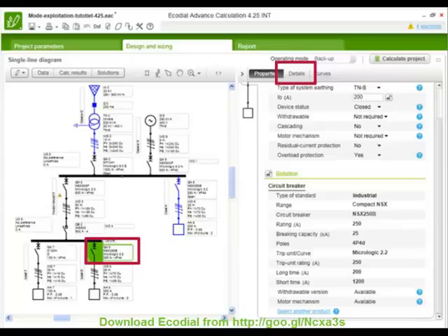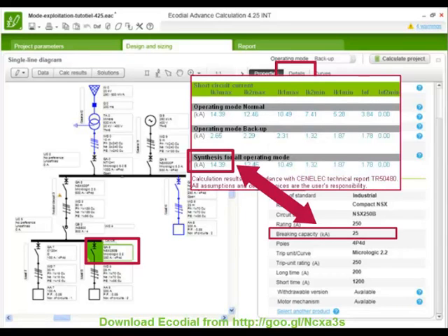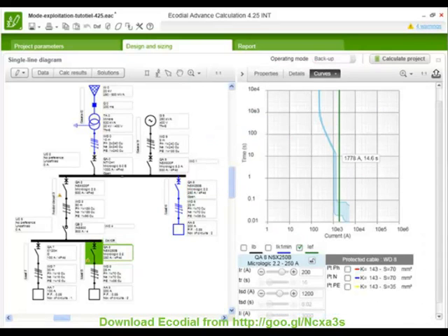Scroll to the Short Circuit section of the calculation note. You find the calculation for normal mode, the calculation for backup mode, and the global synthesis that you have taken into account for circuit breaker sizing and settings. If you select Curves View, you can compare the circuit breaker short delay threshold with the calculated value of earth fault current, Ief.